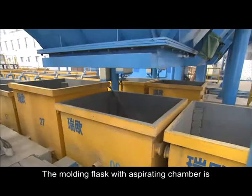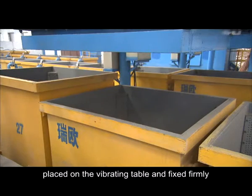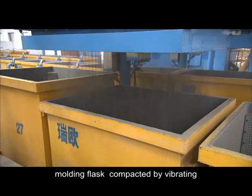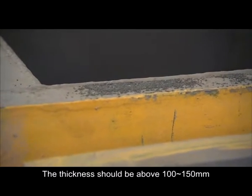Bottom sand. The molding flask with aspirating chamber is placed on the vibrating table and fixed firmly. Some sand is filled in the bottom of the molding flask and compacted by vibrating. The thickness should be above 100 to 150 mm.